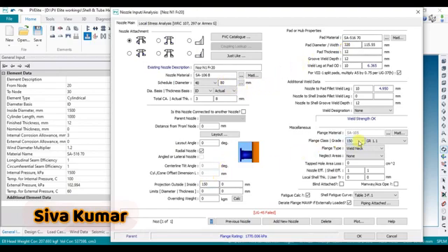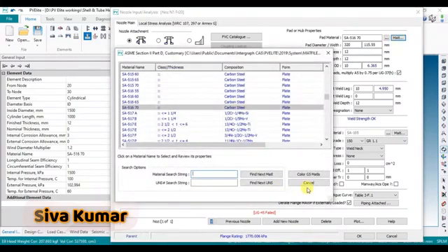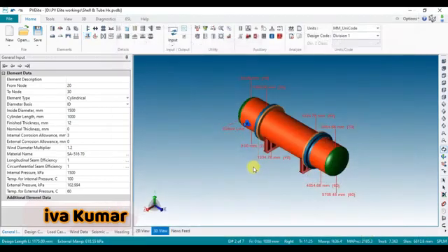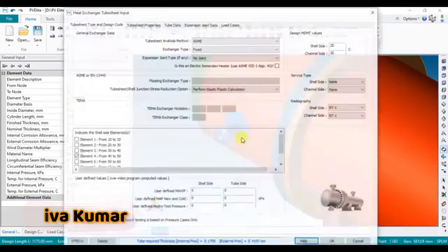So here we can choose this flange class and the grade, and then distance from this. Okay, from node it is 0. Can enter 500. Now if you want to change the material, you can change it here. Here you can enter 12. There is no area calculation. This is a small opening. Okay, you can enter 10 and check. Click OK. So see, this is how it is created.